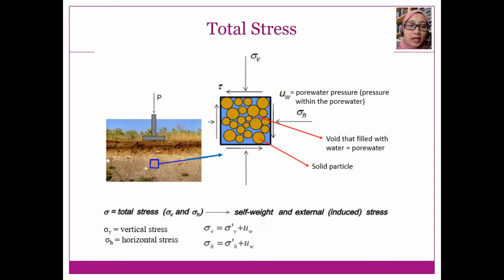As mentioned in the previous slide, the total stress includes all the pressures on top of the soil element, including the weight of the soil itself and also the weight of the water. Let's say this is one point of the soil sample that we zoom into.